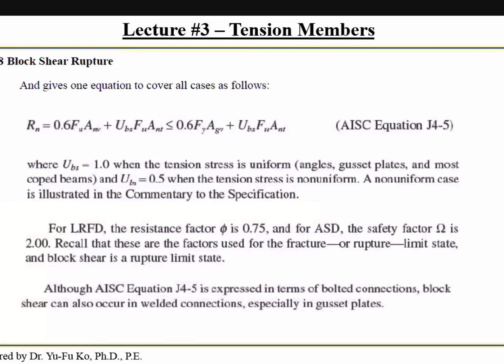For block shear, based on LRFD, the resistance factor phi is 0.75. For ASD, the safety factor omega is 2.0 for block shear rupture calculation.